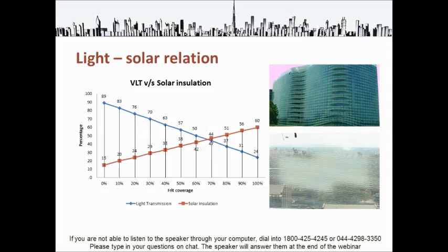This can be strategically designed in terms of reducing visual discomfort. For example, the vision panels can have specific kinds of designs on top of the glass which will reduce the direct light, which creates visual discomfort. At the same time, it can also reduce the amount of heat gain, so the cooling energy is reduced. Here is one typical example which I have shown.